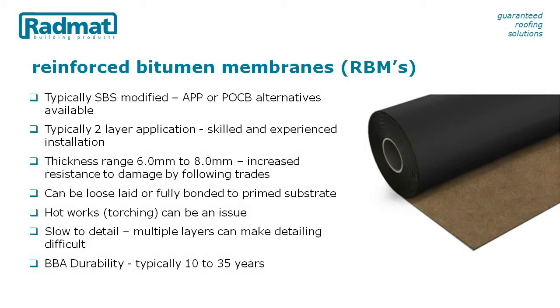Thickness range 6 to 8 mm. Increased resistance to damage by following trades. Can be loose-laid or fully bonded to primed substrate. Hot works, torching can be an issue. Slow to detail. Multiple layers can make detailing difficult. BBA durability typically 10 to 35 years.